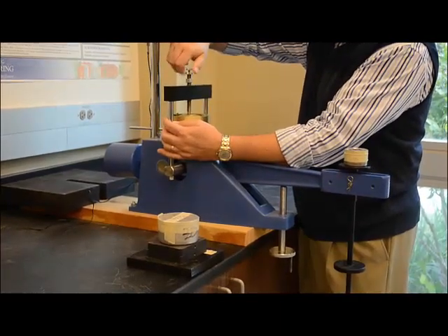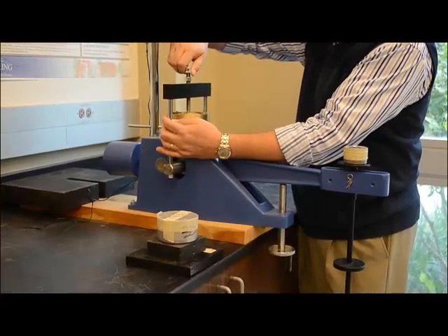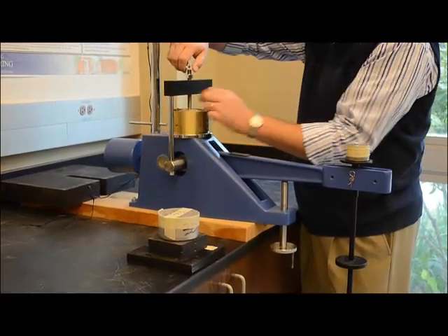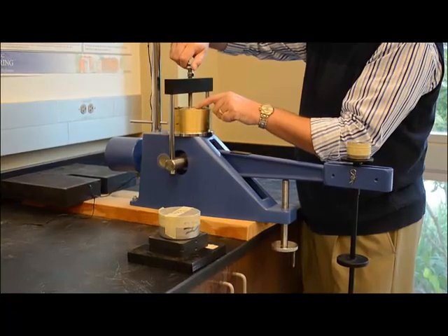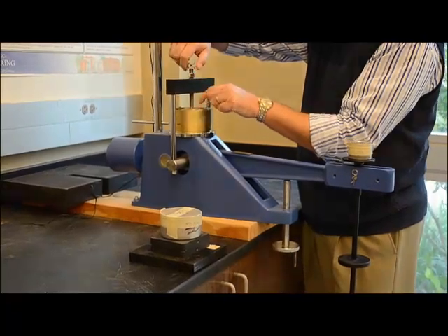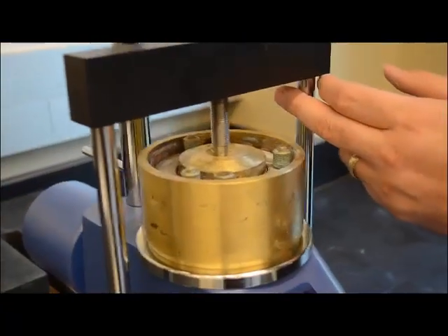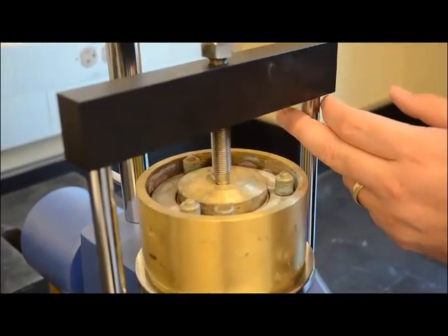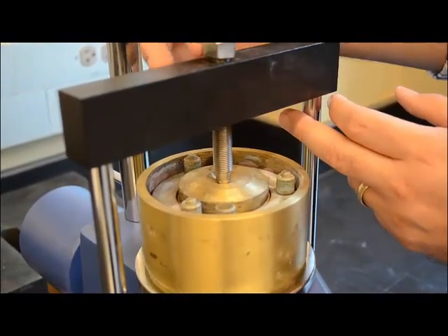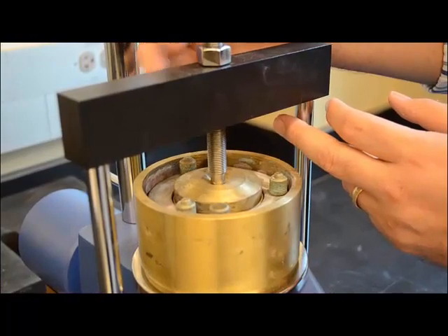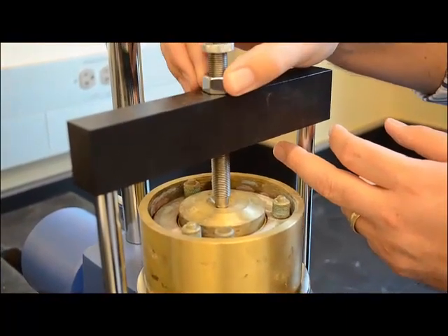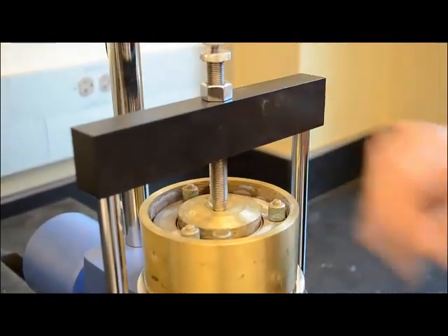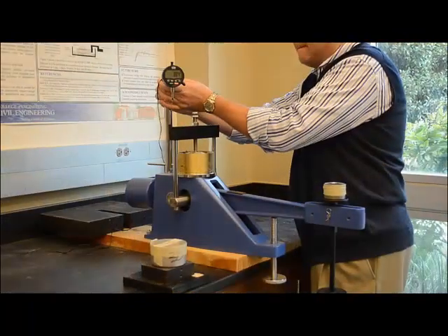down into the concave piece of the top cap to where it fits in nice and snug, but it doesn't put any weight on the soil sample itself that's not measured. We put that down in place perfectly into that concave piece, and then we tighten that nut there to put everything in place just where everything is aligned, but no weight is actually on the sample itself.